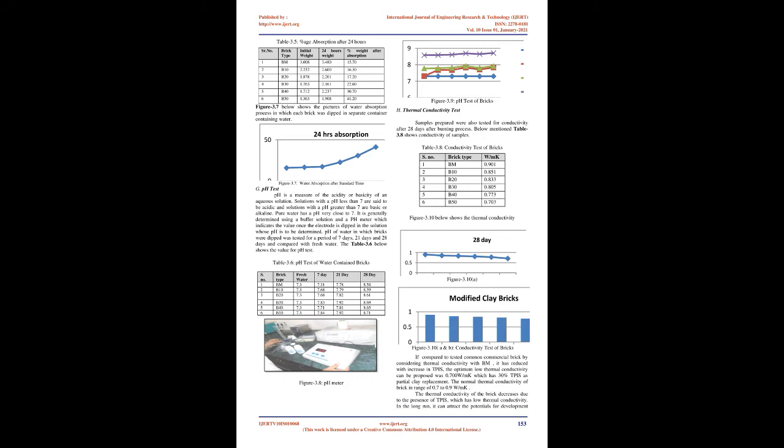1. The use of TPIS has a highly negative effect and reduction on the compressive strength at all ages of the test in set number 2 mixes, MCTPSC, i.e. partial replacement of cement with different percentages of TPIS. This effect increases relatively with the increase of TPIS replacement. This behavior may be because of the inert or non-cementitious properties between the TPIS and cement paste, mainly attributed to the non-reaction of TPIS. At initial replacement of 5 to 10% there has been a decrease in strength within permissible limits, but on higher replacement it was substantially high.